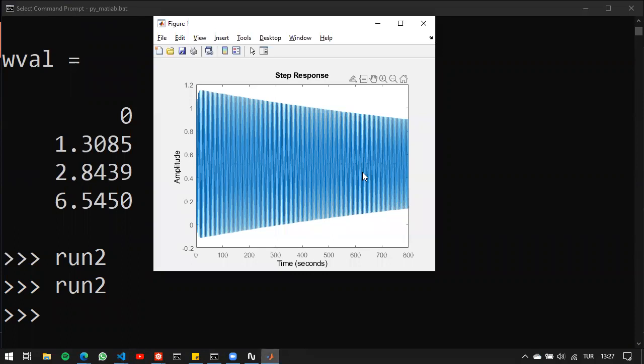And the reason for that is basically we have 1 zero on the right half plane, 1 pole on the left half plane. And as you already know from the root locus plotting method, all poles try to go to zeros. So if you have 3 zeros on the right half plane, 3 poles will eventually go to those zeros. Therefore you will have j omega crossings because you start on the left half plane and you end up in the right half plane.